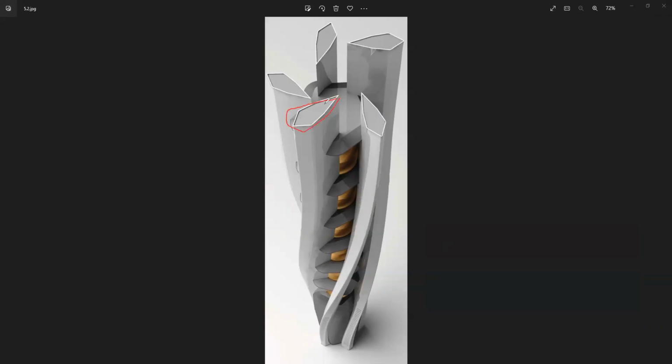But this time, when you are rotating, the center of rotation is not inside the polygon, it's going to be outside. You'd probably have the center of rotation somewhere here. And also, if you notice, there is no scaling. The entire form has the same size, so no scaling. You just move and rotate it. After rotating, you maybe do an array polar to get 5 copies of it. So this is another interesting example, which I think is a slight variation from the steps we have done.